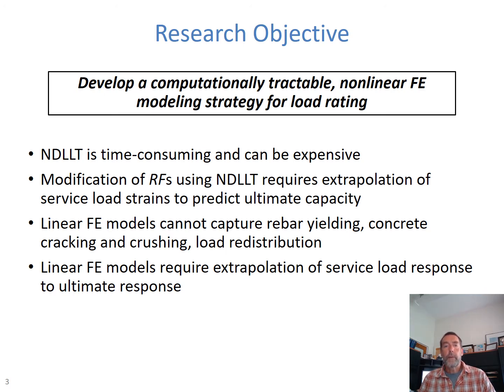And when we modify rating factors using non-destructive live load testing, it does require the extrapolation of service load response to predict ultimate capacity. That inherently is going to introduce some errors in the process. Similarly, with a linearly elastic finite element model, we can't capture rebar yielding, concrete cracking, load redistribution, and those models also extrapolate service load response to ultimate response. So they suffer a bit in terms of the gain that you can achieve in rating factor.